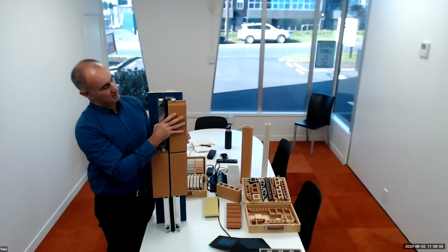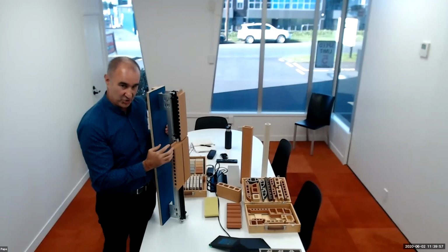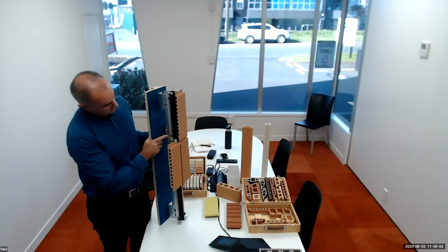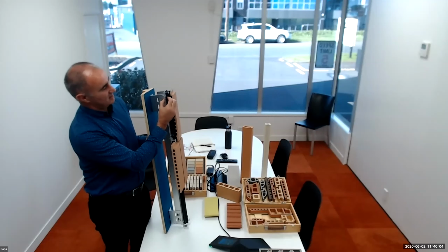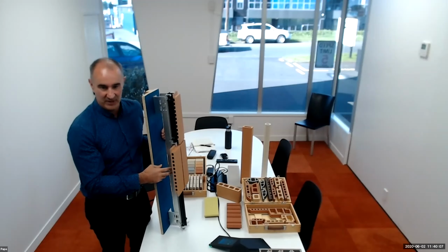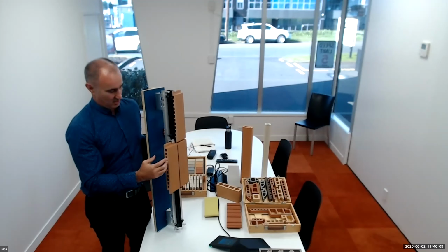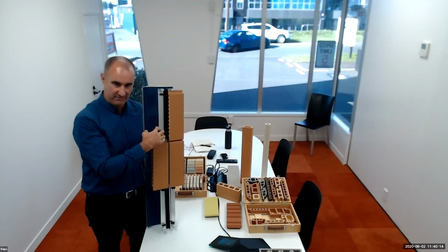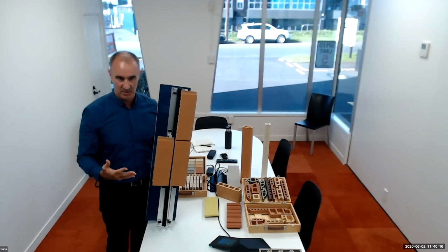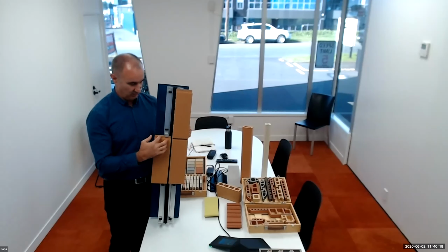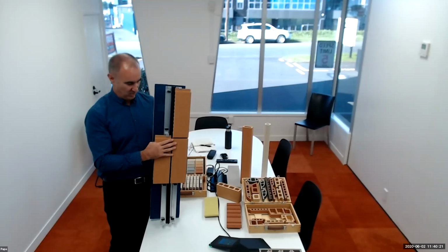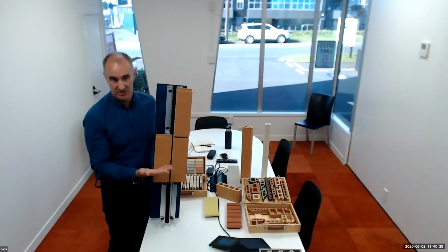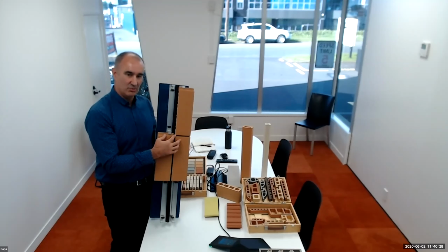I should say they're more restrained as opposed to mechanically fastened, right? These small clips just have little gaskets that compress as you fit the tile into the system. What that allows is the tile to move within the frame. It's not mechanically fastened to the frame. So any seismic movement, any wind load movement, that sort of thing, the tiles are free to move. Obviously I can't move it too much. It's got to take a heck of a lot more force than I can generate, but that's the reasoning behind that.